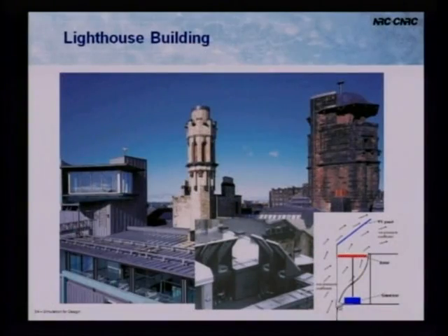And how do you actually collect the heat from the PV panels? They didn't integrate that part, so obviously you can't do it here. We had on this south-facing wall, just below here, a vertical array of PV panels. The idea was that just behind, at the bottom there was an air intake, and then the air would come up and be taken into the building. So it was like a preheat. You take the hot air off at the top. Yeah, from behind them.